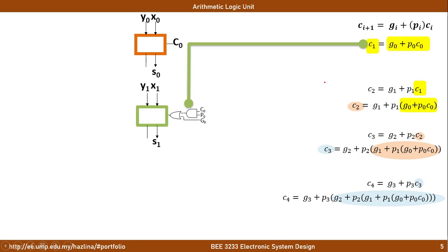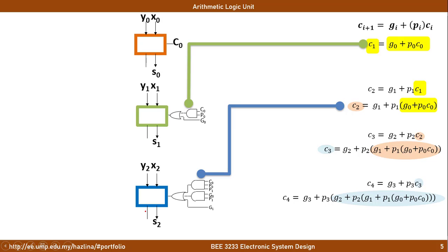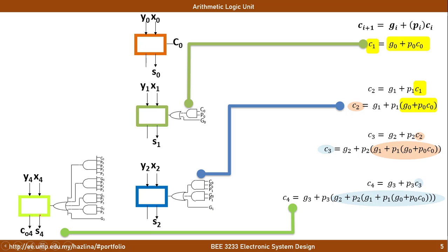G0, P0 and C0. So does the second stage of addition, which is being predicted here at the first instance by knowing the properties of C0, P0 and P1, as well as G0 and also G1. Also, the fourth bit addition is being predicted by the third generated item followed by the propagated item of the third layer.